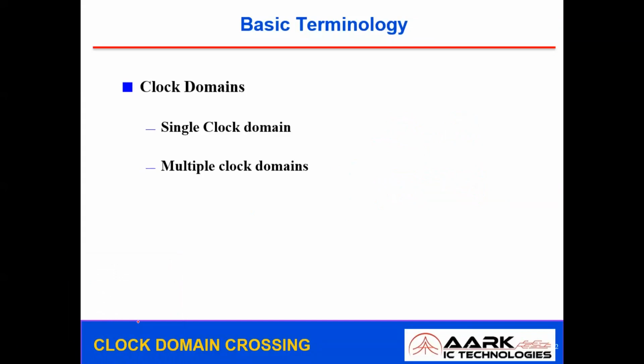When you take an SoC, an ASIC, or anything FPGA related, each block has different sub-blocks integrated together to perform a particular functionality. These blocks might have complex logic, lower complexity logic, or mid-level complex logic. In all three scenarios, each might require a different frequency. When you integrate these three and data is transferred between these blocks, there are multiple chances, or a higher possibility, of data loss. That is what the CDC problems are.